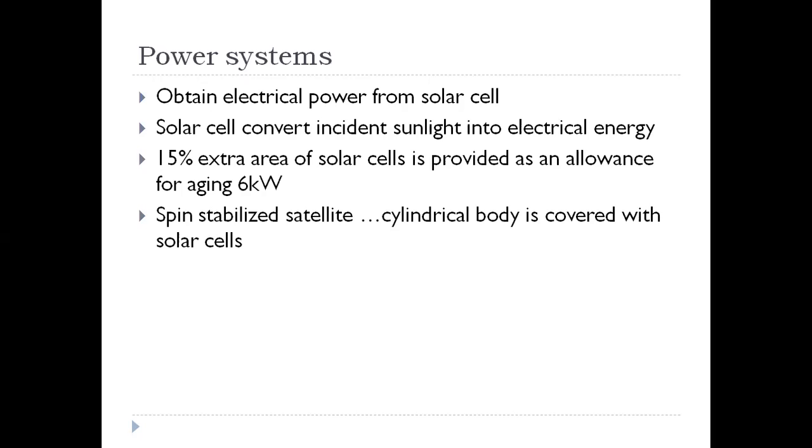To avoid the need for large and heavy batteries, part of the communication system load may be shut down during eclipse. But this technique is rarely used when telephony or data traffic is carried. TV broadcast satellites may not carry sufficient battery capacity to supply their high power transmitter during eclipse and may shut down. By locating the satellite 20 degrees west of the longitude of the service area, the eclipse will occur after 1 am local time for the service area, when shutdown is more acceptable.